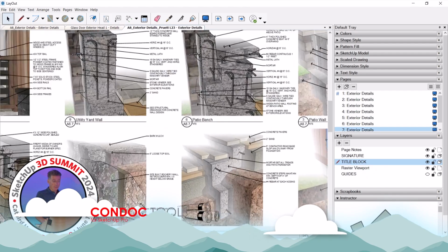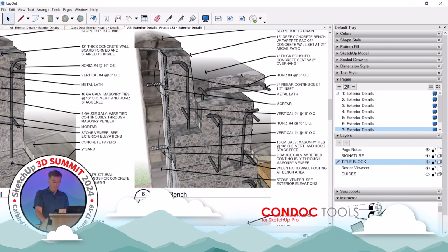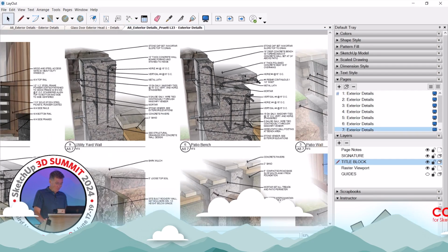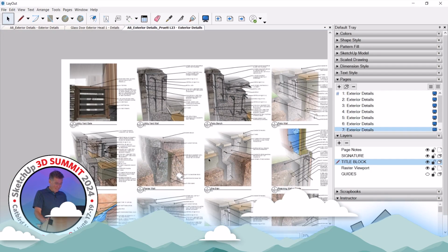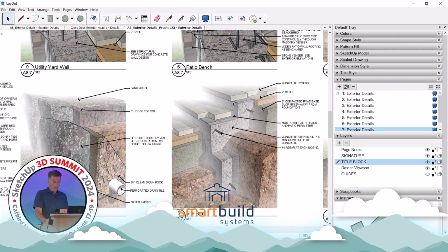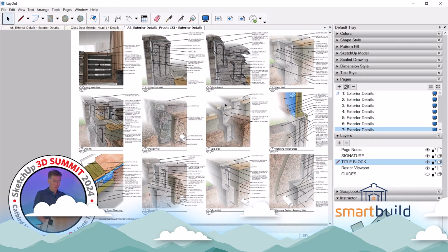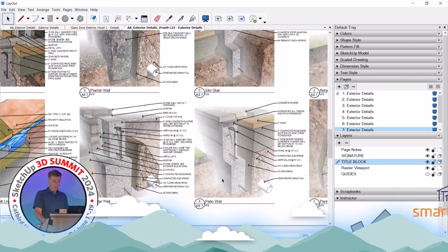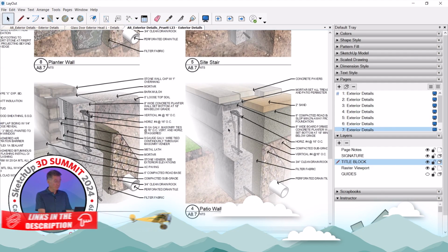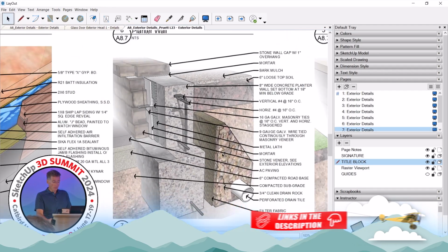You know, little details like this are all custom, where we have a concrete bench. So this is all cast concrete with architects reinforcing, probably way overdone, but yeah. And then, you know, the stairs as well, where the stairs are concrete with a paver that is basically mortared down to the concrete. This will be a patio edge where we're showing board form, exposed concrete. This is that planter wall that has a stone veneer to it on concrete.